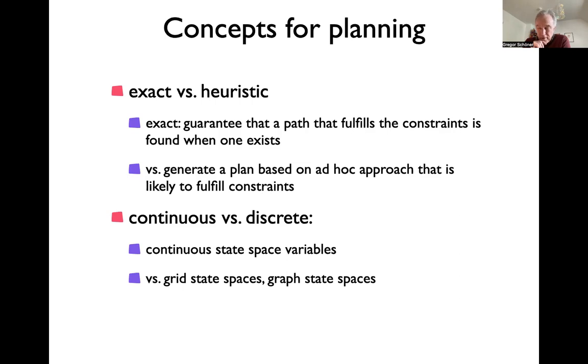There is a field of vehicle path planning that is about exact solutions, where you usually have to make some assumptions about the world. Some of these solutions use certain kinds of mathematical idealizations. For instance, there's a famous approach where you're using essentially Poisson's equation, where you write down a potential where you can guarantee that the only maxima are the points that you specify as maxima, and so they're not artificial maxima or minima, and so in some sense you can prove that you will fulfill the constraints. So that's really more for the mathematical theory of that.